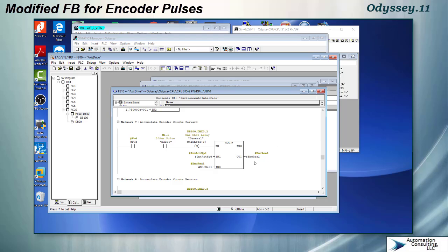Now in real life, of course, your encoder would be based on how many pulses the encoder was, and every time the motor revolved one time, you would get that many pulses, and you would accumulate pulses into a high-speed counter card. That high-speed counter card operates independently of the program. So if I want a signal to come on from the card to say stop at say 10,000 pulses, it's going to do that regardless of the position in the scan of the PLC.